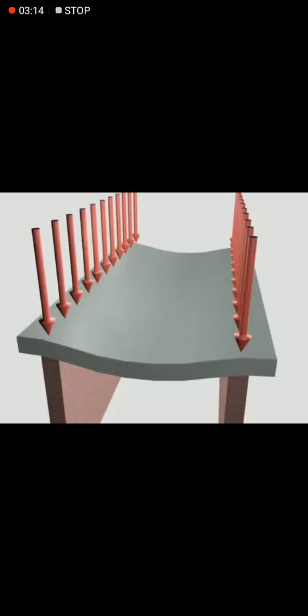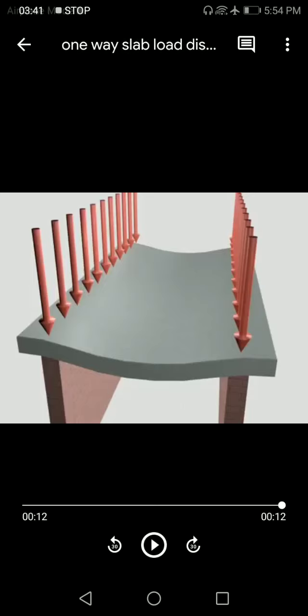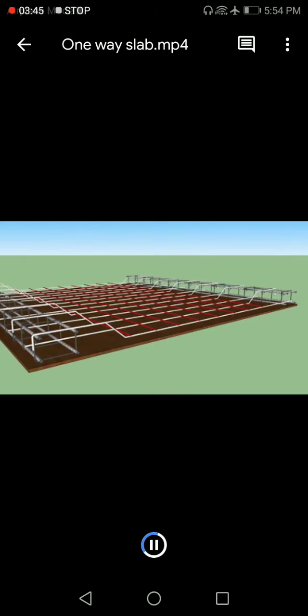The transverse direction, that is the direction perpendicular to the main reinforcement, is called the distributor. The reason the distributor is provided in the slab is to reduce the shrinkage of the slab. That reinforcement is called the distributor. I will show you. Please watch the reinforcement very carefully.